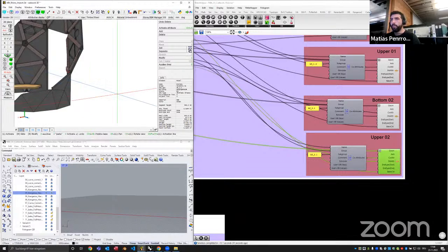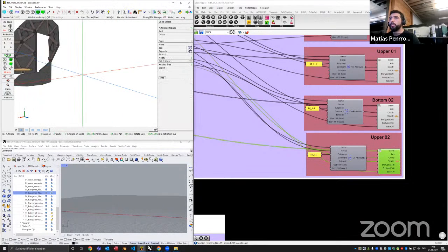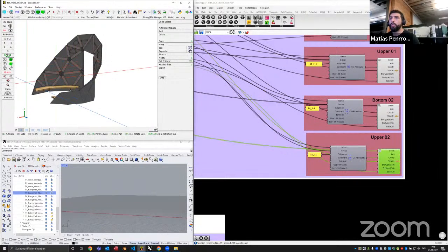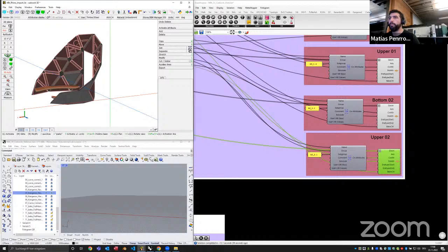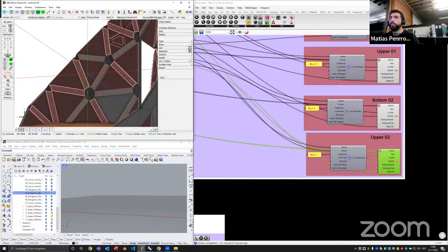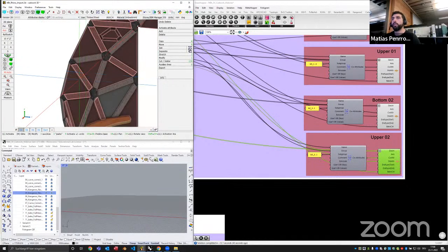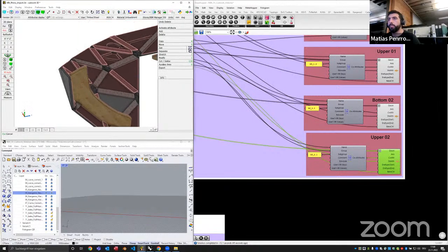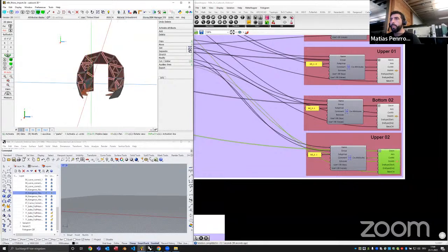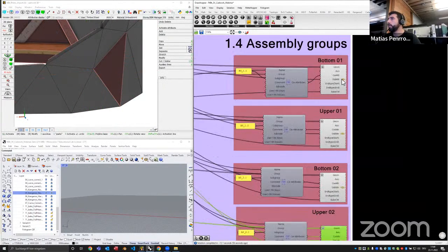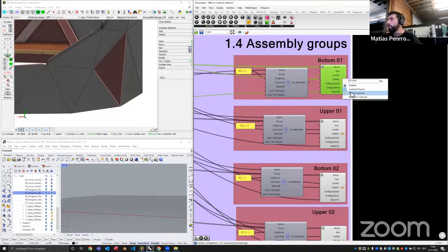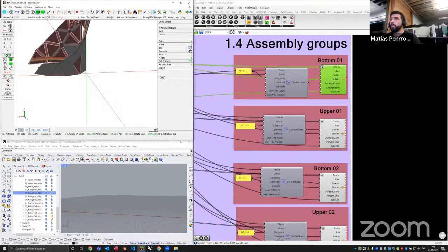And if you can see this here in Cadwork, another aspect is to check the reference panel and surface for the nesting aspect. So these red surfaces mean that this is the reference panel. This will be on top, so the machine will do the operation on this side. Here you may see that there's a couple of them that are wrong. So if I were to check this, I would take this to Cadwork, the group.